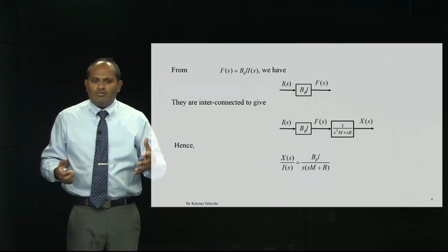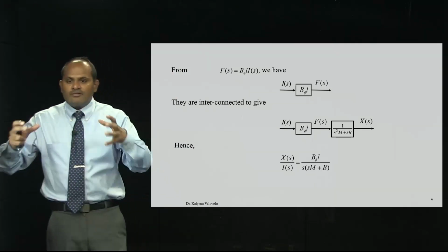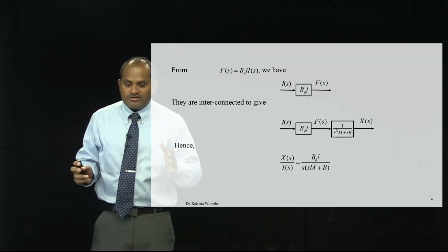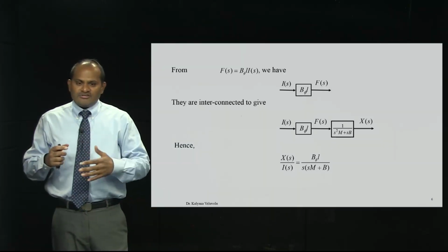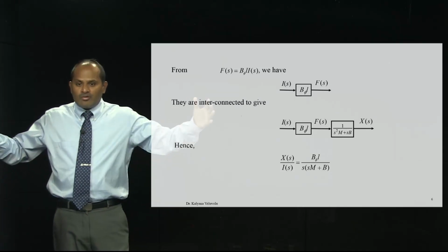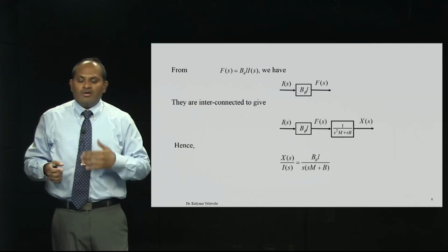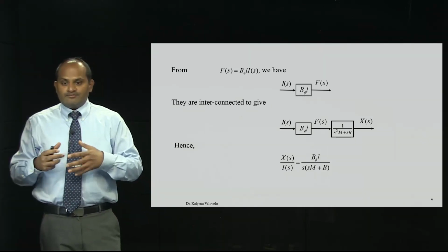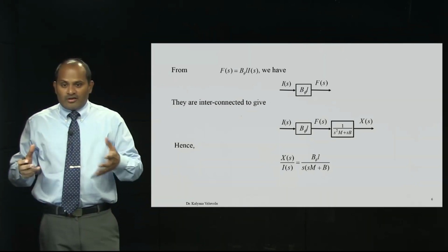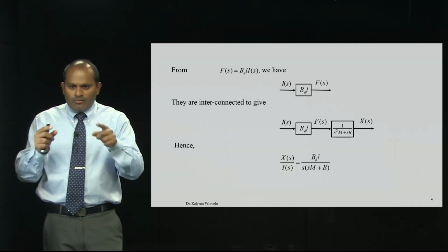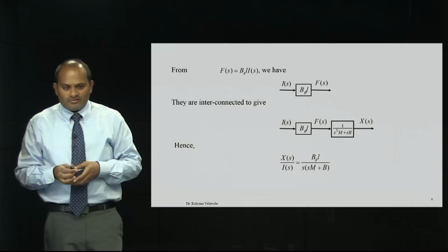The beauty of block diagrams is we can interconnect many blocks and make them into one single expression. Block diagrams give us the flexibility to break into several parts or combine into one part, like we learned in block diagram algebra. We can solve a big block diagram into one simple block, or break a big block into several individual blocks.